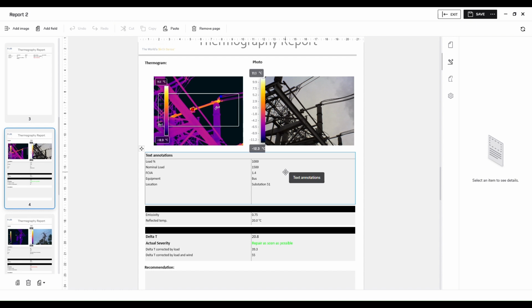Of course, all the standard object parameters such as emissivity must be input correctly. And finally, Box 1 must envelop the hotspot of interest, and Spot 1 must be on a suitable reference target.